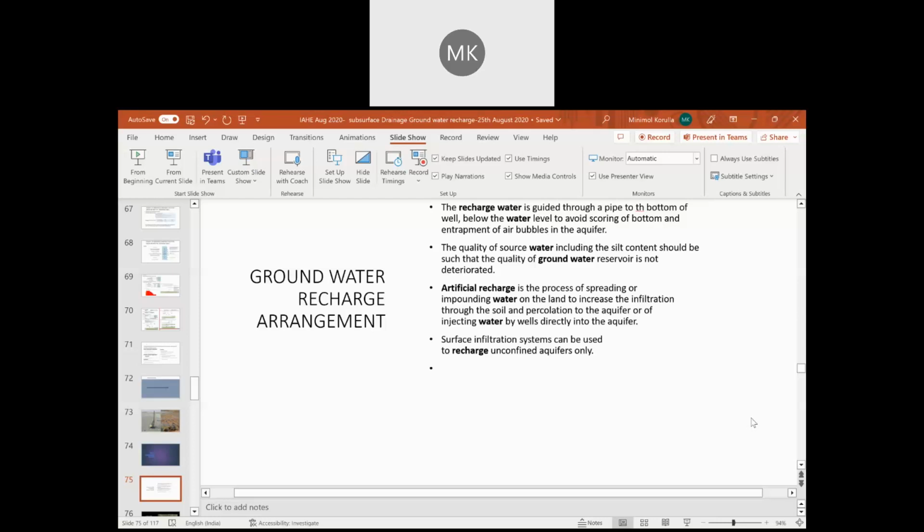And for the design, I will recommend either going for IRC SP59, the design criteria, or you can go for IRC SP42 for the drainage geocomposite. Definitely IRC SP59. For the general drain, it is better to go for IRC SP42.